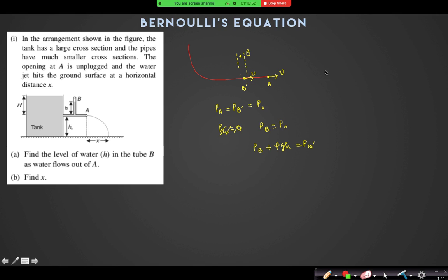I am saying that if this is a tube, take this point A and take this point B. So velocity of the points A and B must be the same. And if you apply Bernoulli equation, you can say then it will be PA plus half rho VA square plus rho g H equal to PB plus half rho VB square plus rho g H. H is 0, not a height difference. So that is equal to PB plus half rho VB square. VA, VB are same. So PA and PB are same.